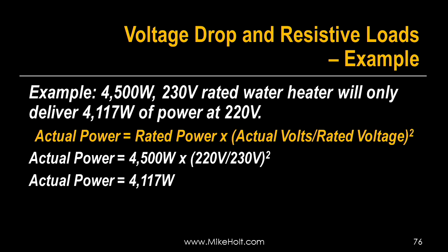It just so happened about a week ago, I was in my little room on the side of the house, Brian, where I have my fishing gear and everything like that. I looked at the water heater, and I looked at the nameplate rating. It just happened to catch the light, and it gave me the power at 230, and it gave me the power at 208. Let's go with this, guys. If it gets 4,500 watts at 230, what is that water heater connected at 208?